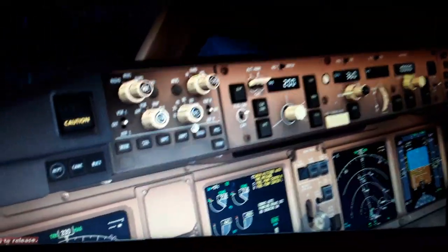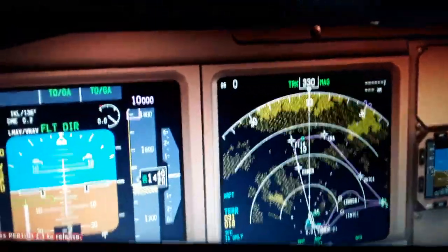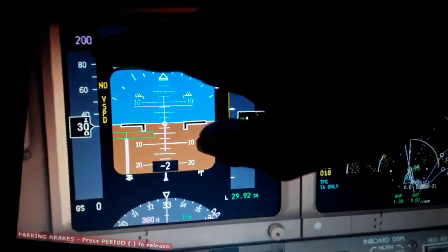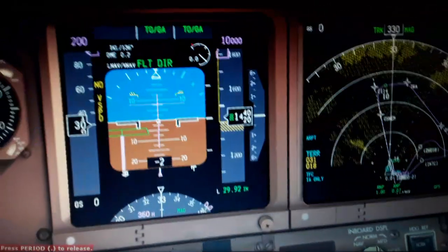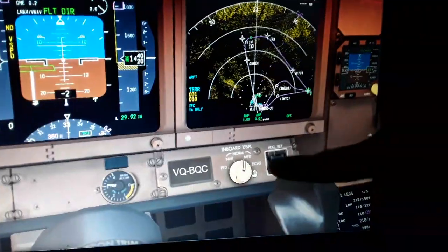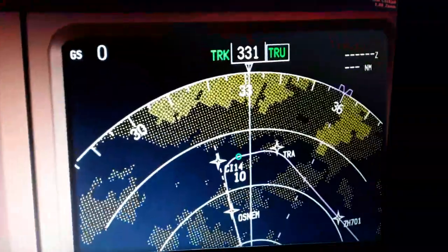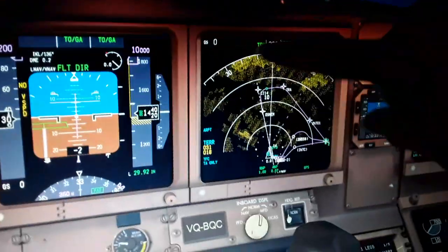We have also the radar screen. You can see the terrain elevation and the waypoints we have to follow. So we have here the display. You can see the airspeed indicated, the airspeed selected from the autopilot flight director system panel, the ground speed, the pitch attitude indicator, the magnetic heading and track here and here, magnetic north pole, true north pole, magnetic variation depending on where we are in the world. So now we have the normal, now we have the true, which is the geographic north pole, and it's 2 degrees offset here. So we change now again, we have magnetic again.